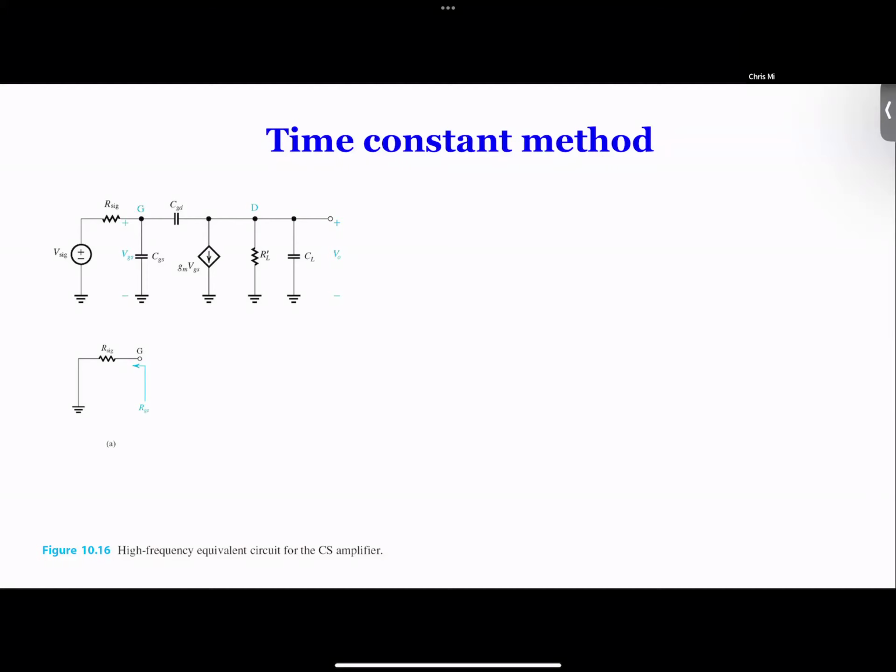So that is already something we simplified. Now if you look at this circuit, we do have 3 capacitors: CGS, CGD, and CL. If you have a BJT, remember that the BJT only changes r pi, and r pi can be in parallel with RSIG, and it actually simplifies to the same circuit eventually. One step, you'll get the same circuit.